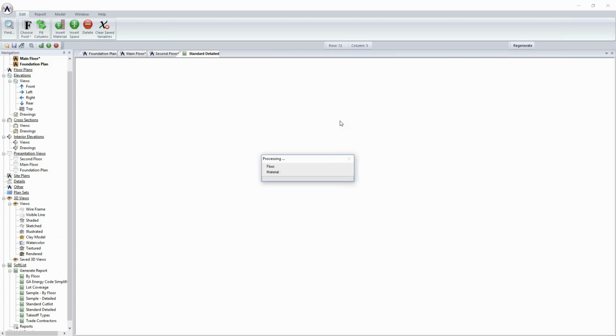I'm okay with that, and I'll click OK to begin the processing of the 3 floor plans. What you're going to see now is it going through and doing the calculations. In a couple of seconds, you're going to begin to see some prompts that come up. These prompts are either going to be warnings or asking for information. Right now I see a value prompt as it pertains to termite protection, which is a yes/no: do I want to calculate for termite protection on the project? If I select no, it's going to push past it.